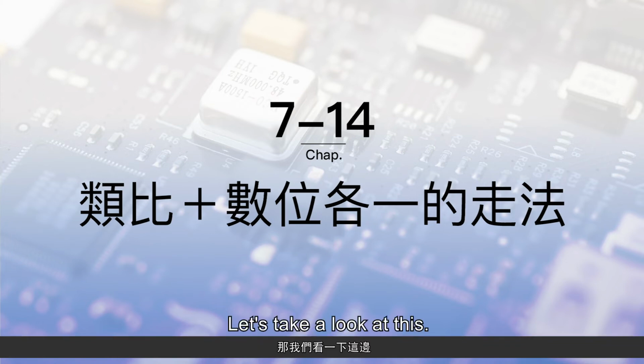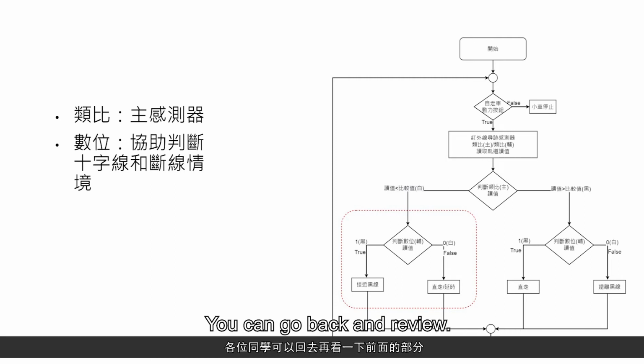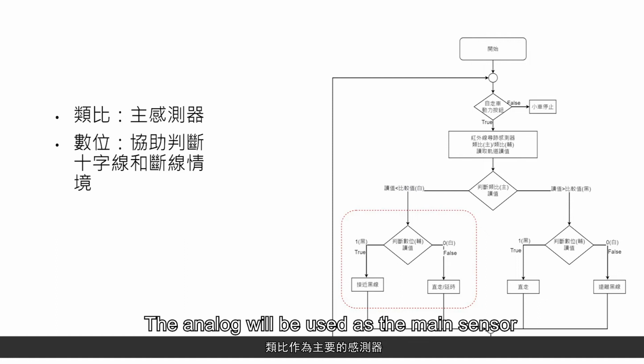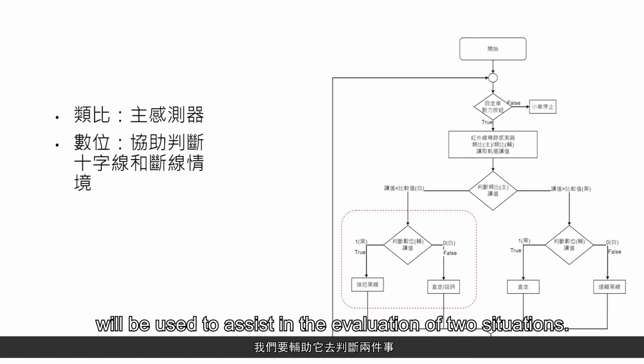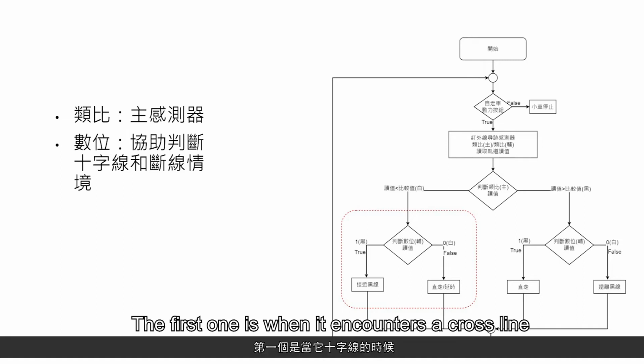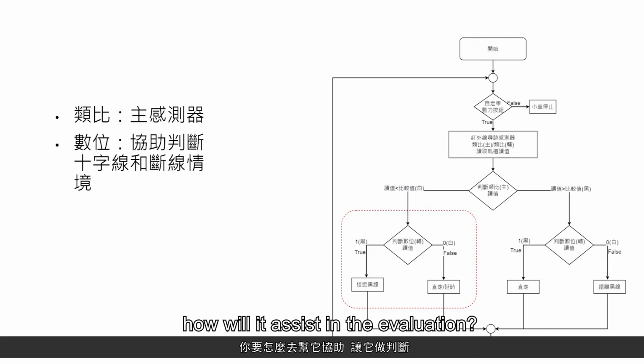Let's take a look at this. We've talked about how evaluation works before, so we will not talk about it here. You can go back and review. Let's take a look at this. We'll divide it into two sides. The analog will be used as the main sensor for tracing. The digital one that was added will be used to assist in the evaluation of two situations. The first one is when it encounters a cross line or a light gap.